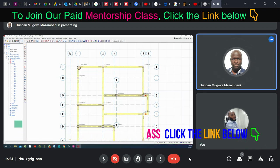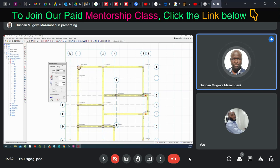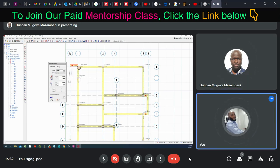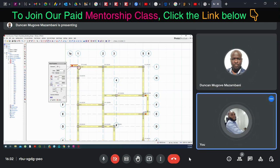For the cantilever going out, you can just choose from grid line 1 and grid line F to put your cantilever beam. So I'm going to put a pin here, from that point to that point. Now make it a center. That place where you aligned it, make it a center. So go to that place and choose center, and then click on update.